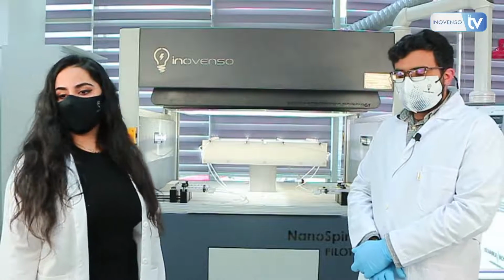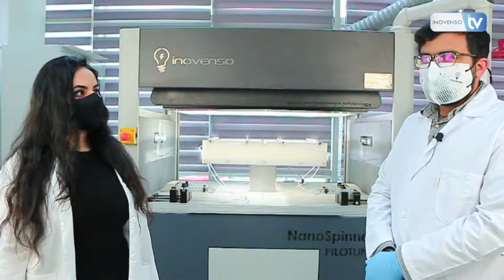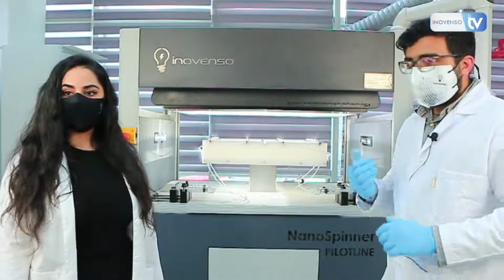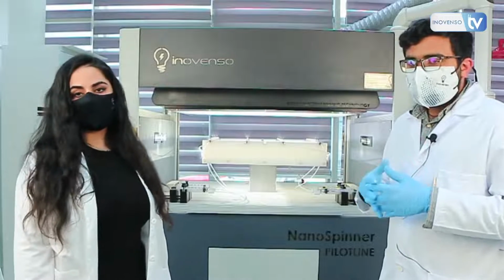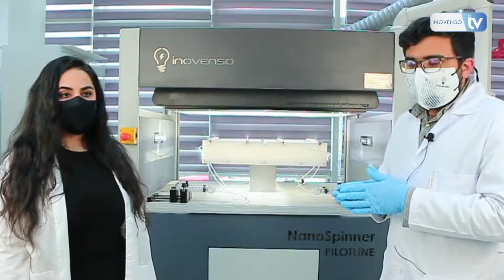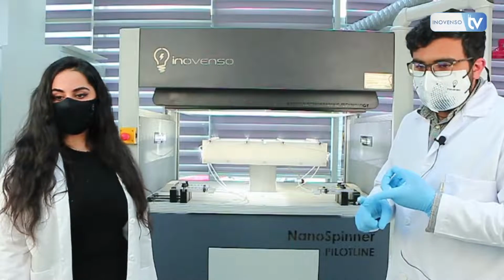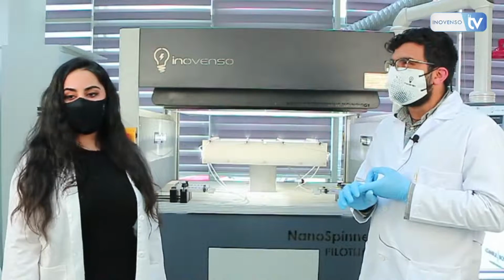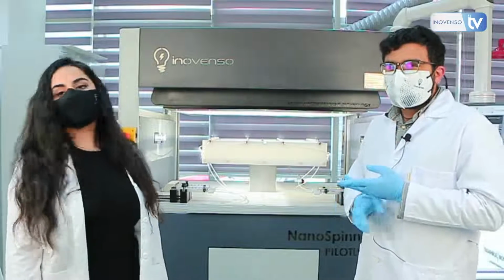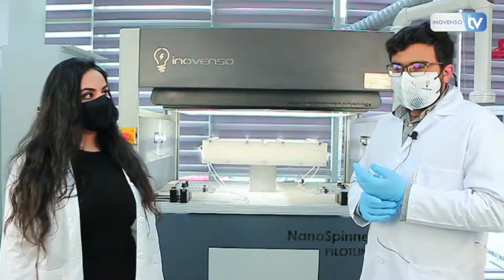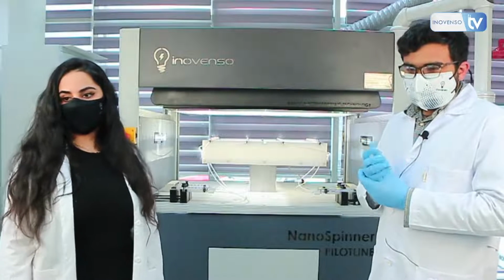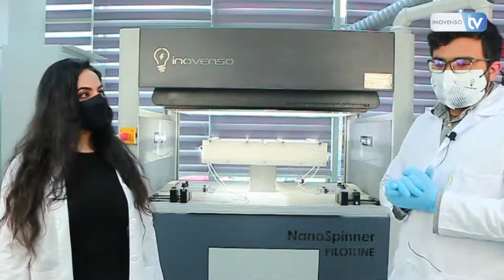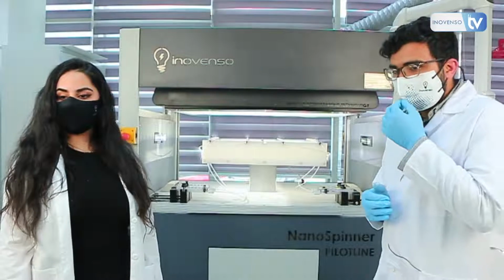What is the quantity of nanofiber produced per hour? So I think we measured this before, but it depends on the polymer type you're using. In our case, when we're using PVDF, it has a particular flow scale, like in meters per hour. So you cannot say the same thing for PVDF or TPU. If I recall correctly, PVDF could approximately produce 53 square meters per hour on the pilot scale. That was for the N95 membrane. Another example is TPU, like 150 grams per hour for the PE 550.